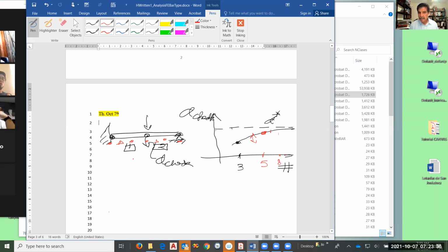Okay, this scheme that I'm showing here is something that we always have to do. And at the end of the semester, when I ask you to complete the project, this is something that you have to do. You have to do a partition of the domain, get some answers, and then do another partition and compare. If the responses are close one to another, that means that your final partition is adequate. If you find that the differences are very large, you have to decide what is large for you, then that means that you have to do another step.